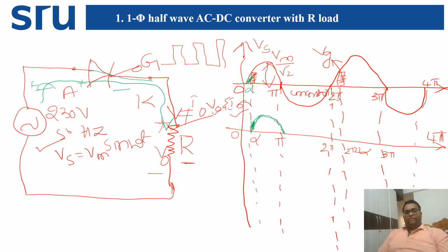Am I right? Then after that, when we are going for the negative half cycle, what will happen here? Instead of plus minus, it is minus plus across the anode and cathode. This will be open circuited, whether it is an SCR or MOSFET or IGBT, anything.